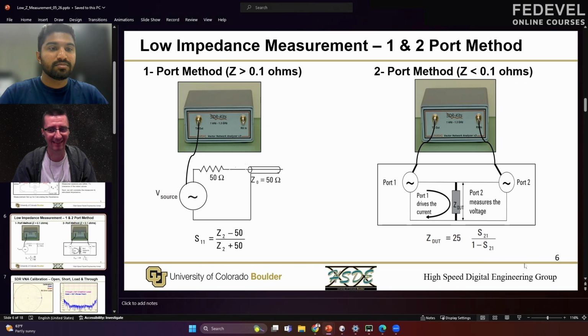So basically we only created the touchstone file, the S-parameter model. Yes, so we have the S parameters, we have the touchstone file, and we'll import the touchstone file in Qucs, and then we'll plot the measured data, and then we'll actually simulate an RL model for this resistor to understand the actual resistance and ESL values for a real component. So again, let's see how we can do that.